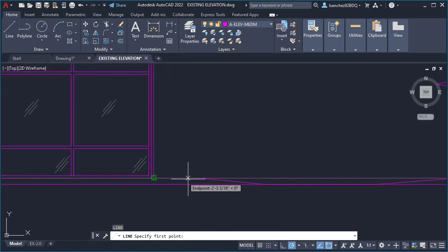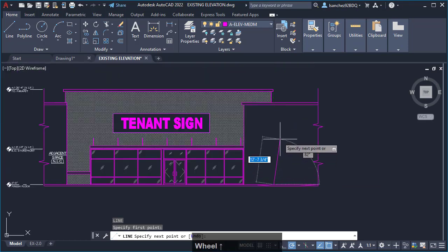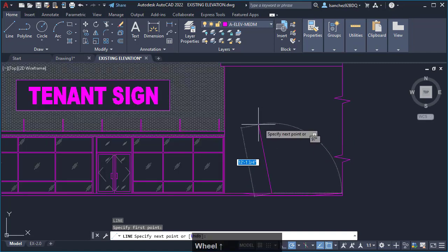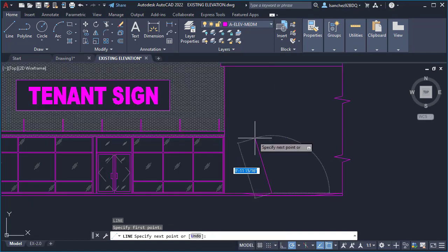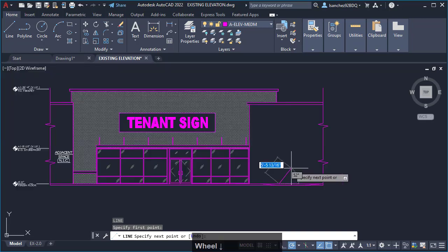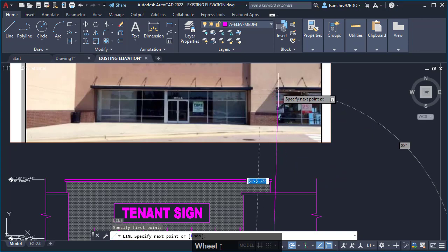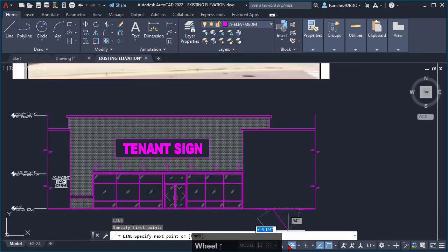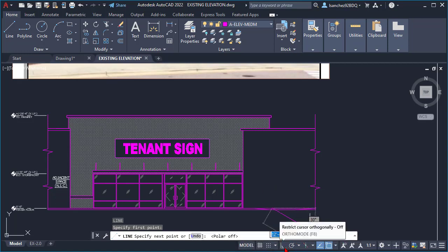Again, hover over this, move it like so, click, and then right now my line can be moved in any angle, but I want to constrain that because for this specific drawing we're mostly gonna use orthogonal lines, right? So let's turn off this polar tracking precision setting, and let's turn on this ortho mode.